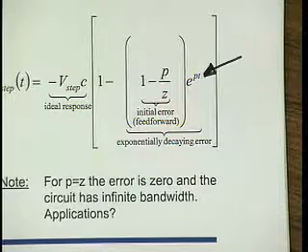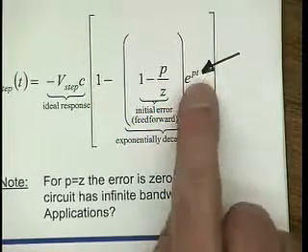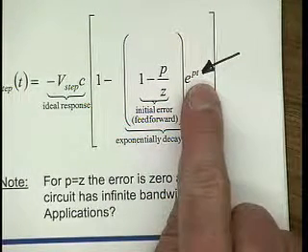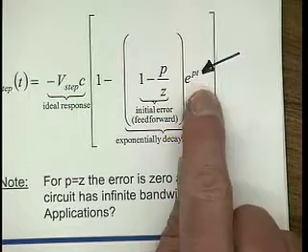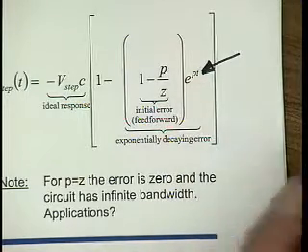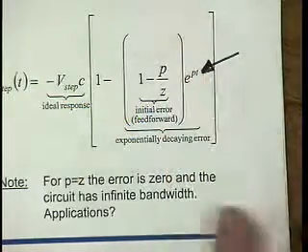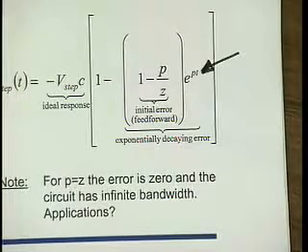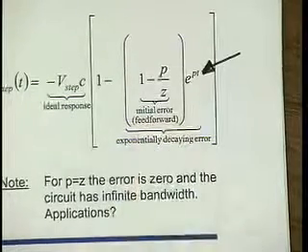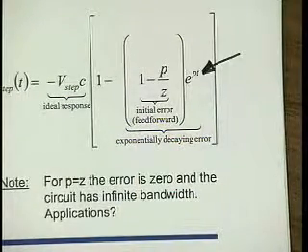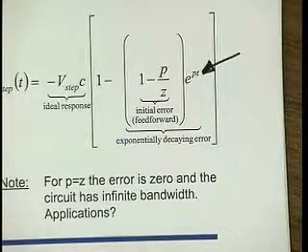Yeah. Make the pole and the zero the same frequency? Yeah, exactly. There are two possibilities, right? What we normally do is we wait for an infinite amount of time, and then this term is going to be, yeah, the pole is negative, so this term is going to be 0. Or, much more clever, P equals C, and this term is 0.